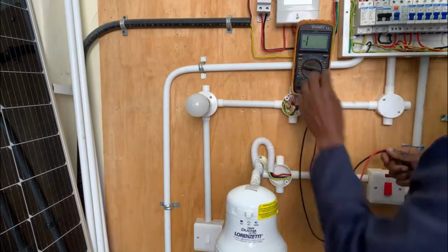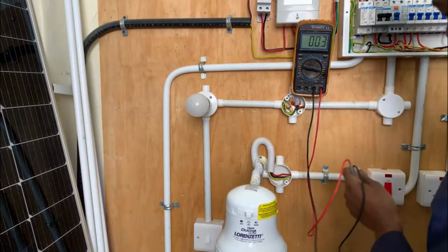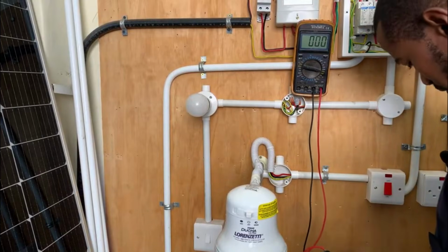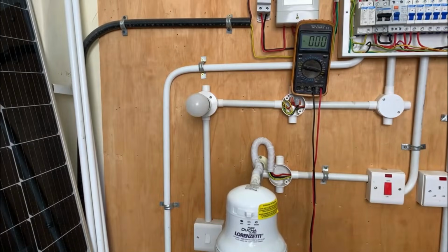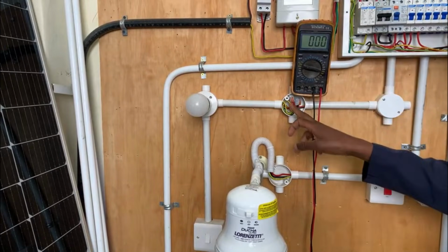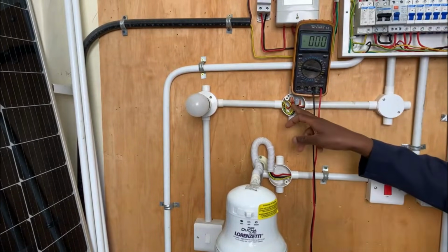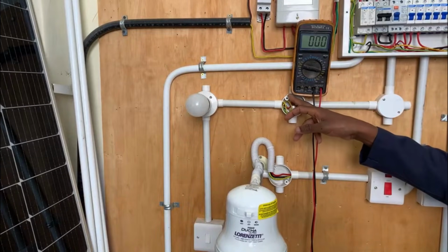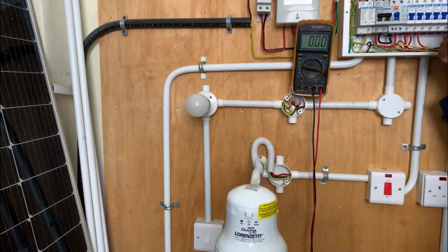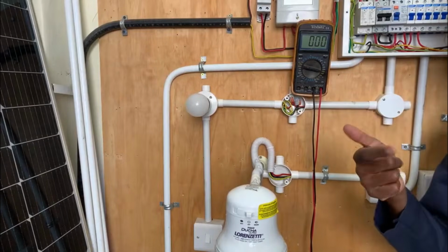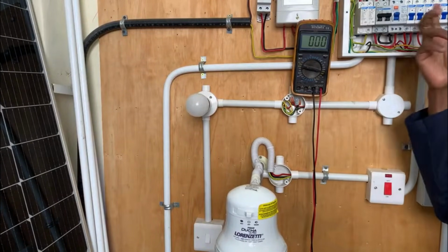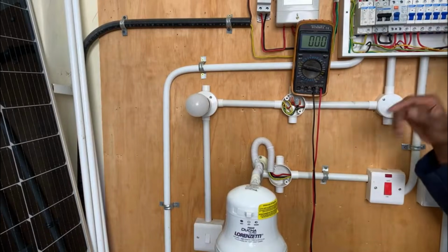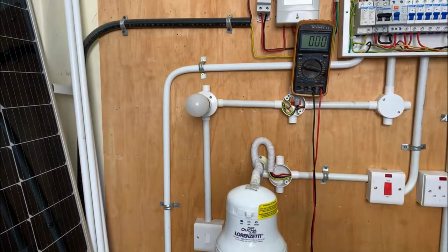So let me just record the voltage and see whether I have 214 from this side, and you interchange it. I'm using my power backup, and yes, so I was saying, if we short circuit the line and the neutral at this point, we can demonstrate how the MCB tripped, assuming that MCB is okay. And then after we sort that one out, we test and then turn the MCB on and then put the circuit, the lights on. So we go ahead and do it.